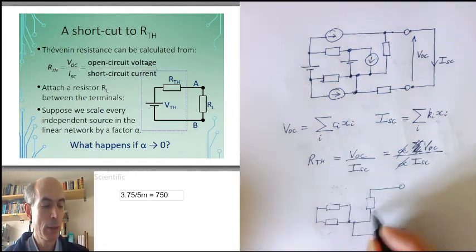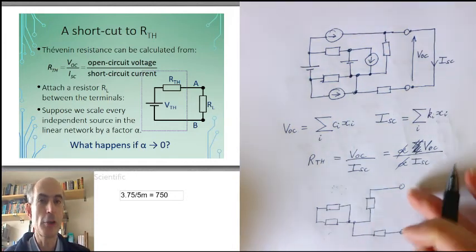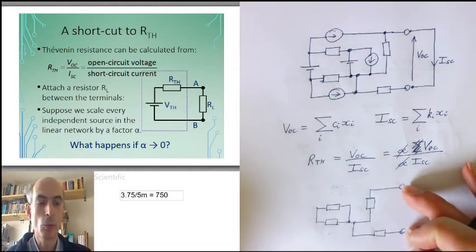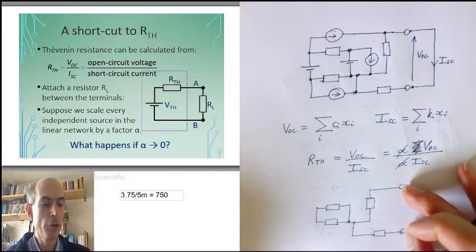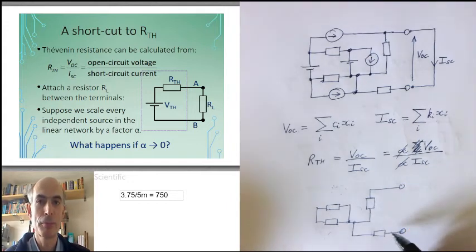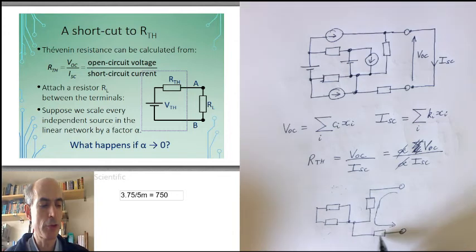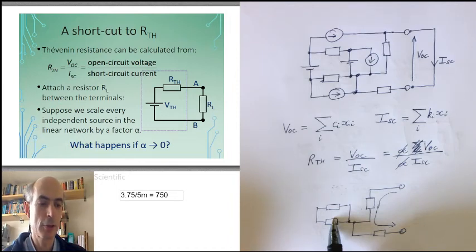Now, if I look at this circuit and ask, what is the equivalent network to this network? Well, this is just a network of resistors. It's going to have an equivalent network, which is just a resistor. The current is going to flow down through this resistor, and back to this terminal here. These two resistors aren't going to take any part in this circuit at all.